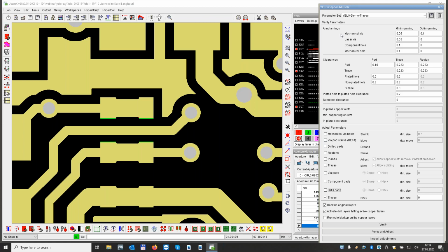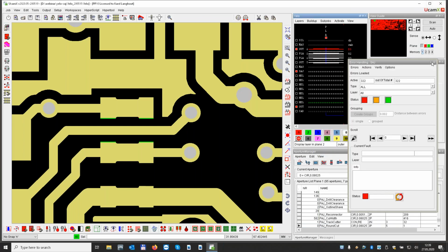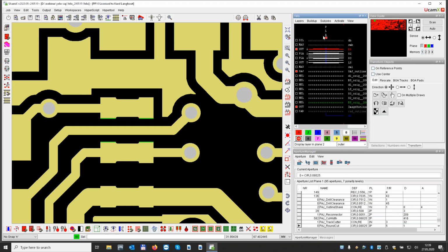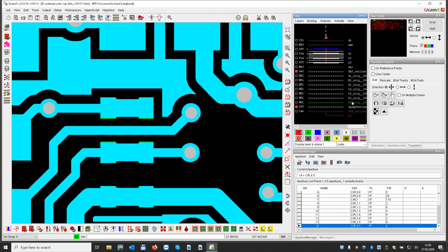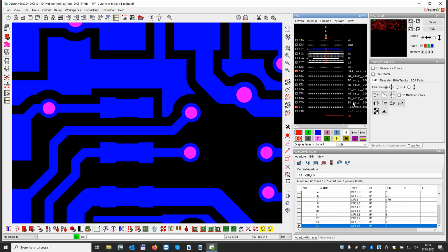So actually, for the preparation, there's only two things that you must do. One is normally something you do anyway, so it's really nothing new, it's an automatism: you enlarge your drill holes, because your customer sends you data for 1 millimeter, you will drill it at 1.1. This is logical. Everybody must do this. And we have a little module for that called the drill tool manager.